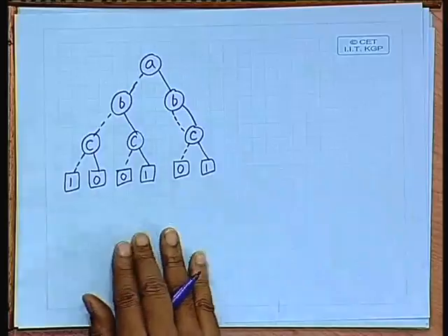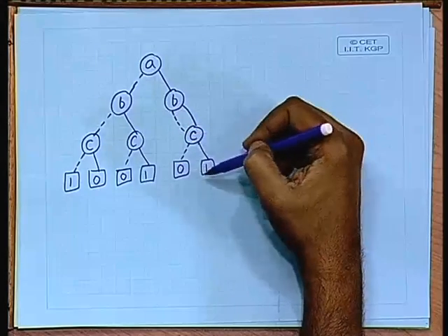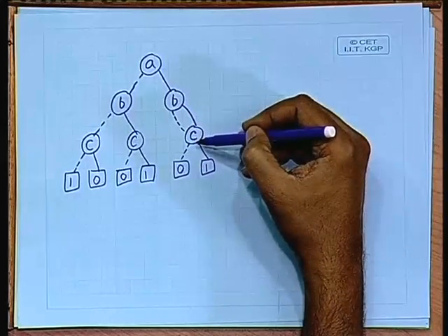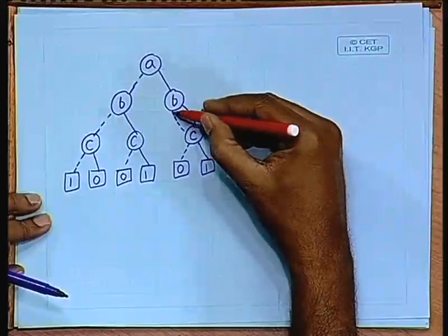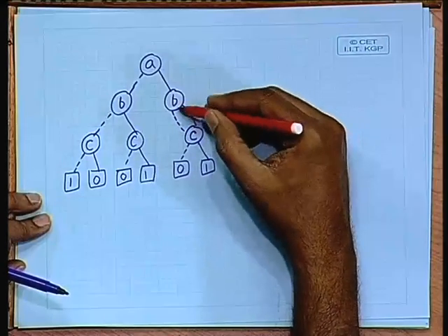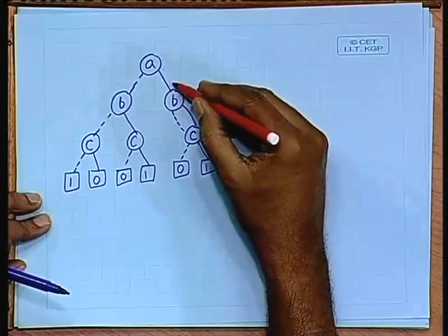This diagram captures the same information, that from B, if you have a dotted arc, you come here, if you have a solid arc, also come here. Since the subtrees are identical, we can keep one copy and point all the arcs to it. Now after doing this, you find that both the complementary and uncomplementary arcs are pointing to the same node. So you can omit B.